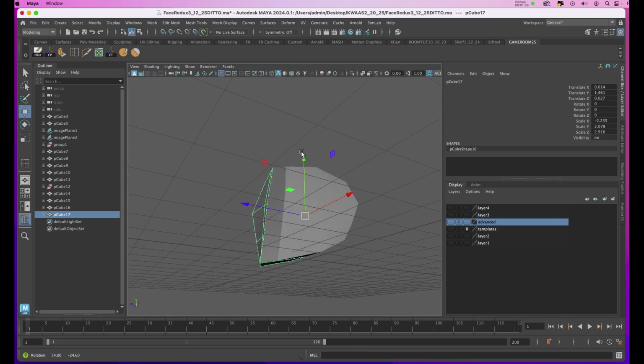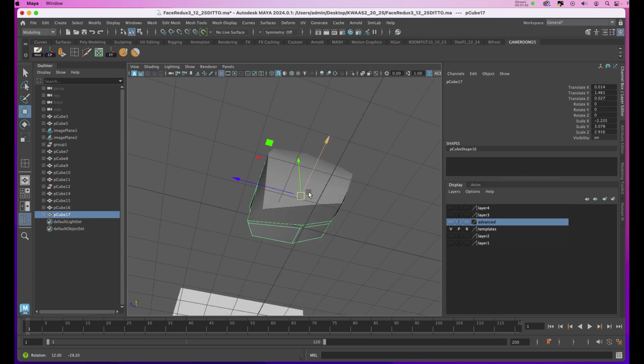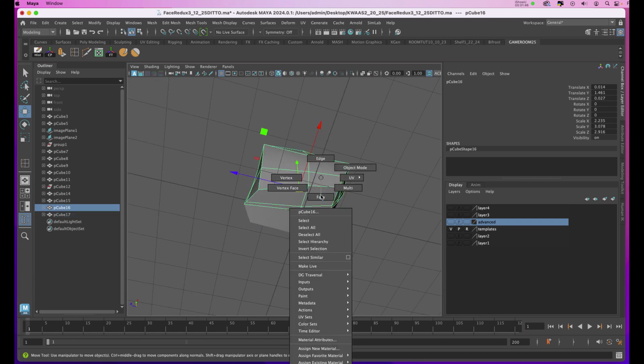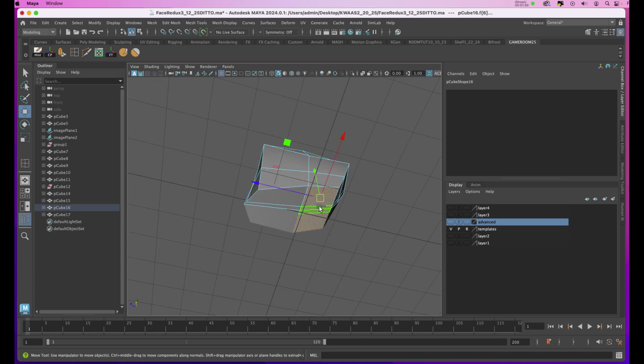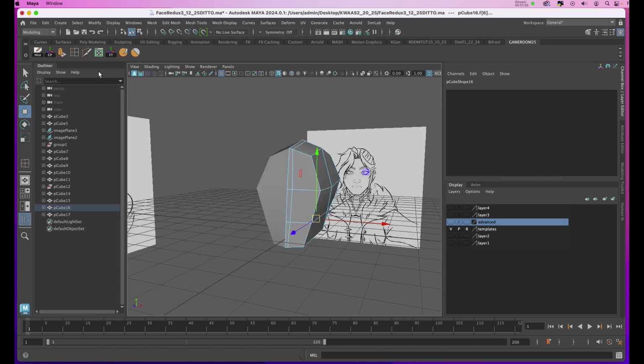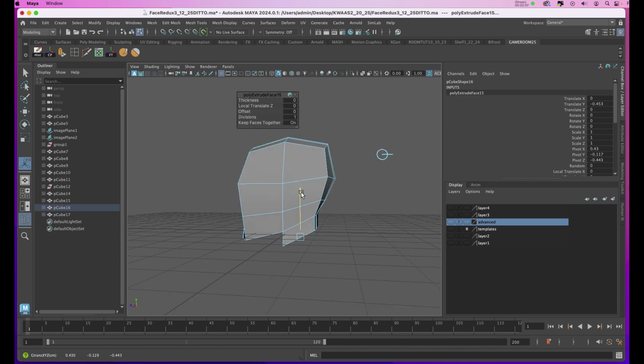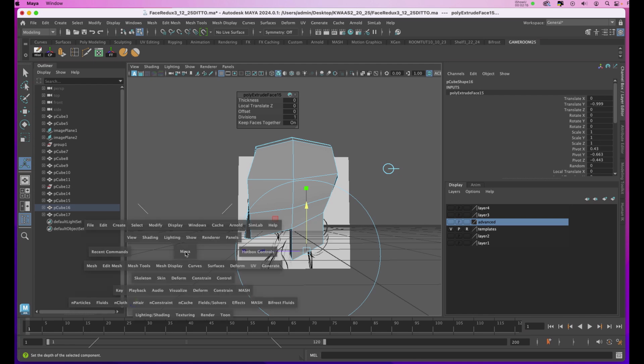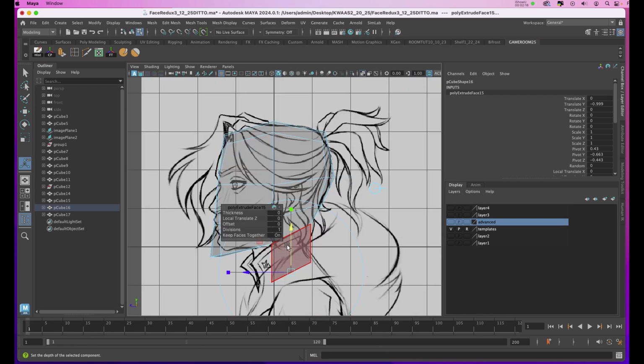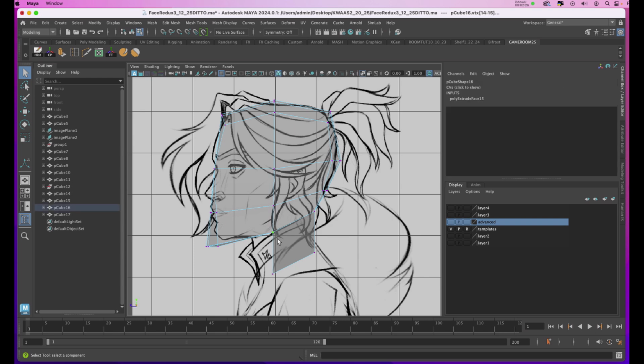Now I'm going to go into my perspective view and add the neck section. I'll select face and select the faces that I want to extrude, and I'm going to click on my extrude button and then I'll center it. And I'll start to introduce this. And again, I'll refer back to my template for position and scale. So I'll quickly go in and do that. And I'm going back and forth from 1 and 3 on my keyboard to see how closely my model is matching.